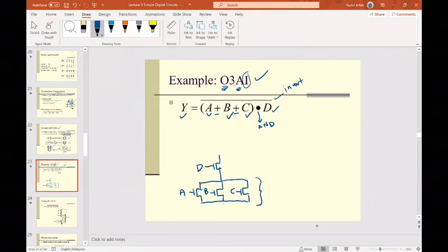And like I said, down here should be what? A source, right? Yep, that's the source. So the source should be connected to ground. Okay, and then the drain, this is the drain, should be connected to Y.